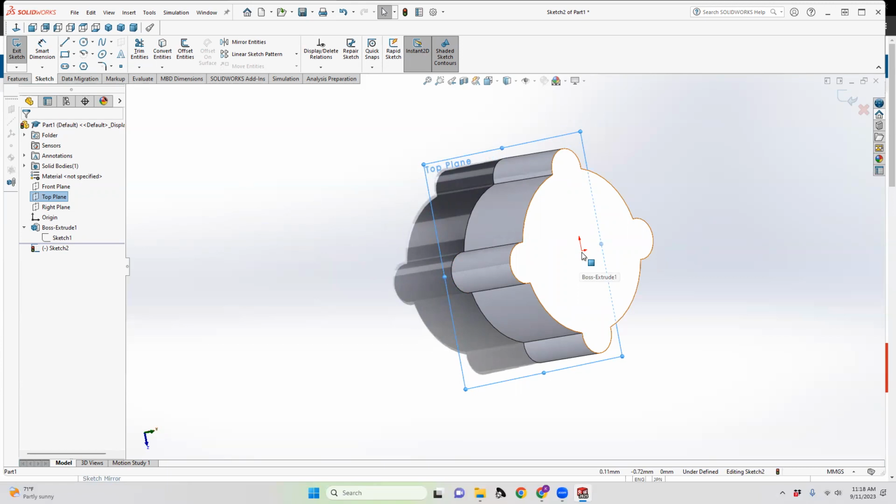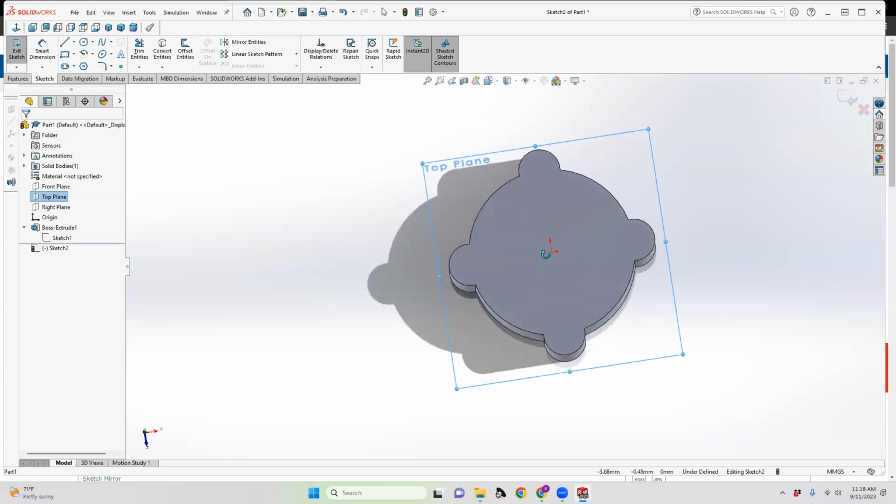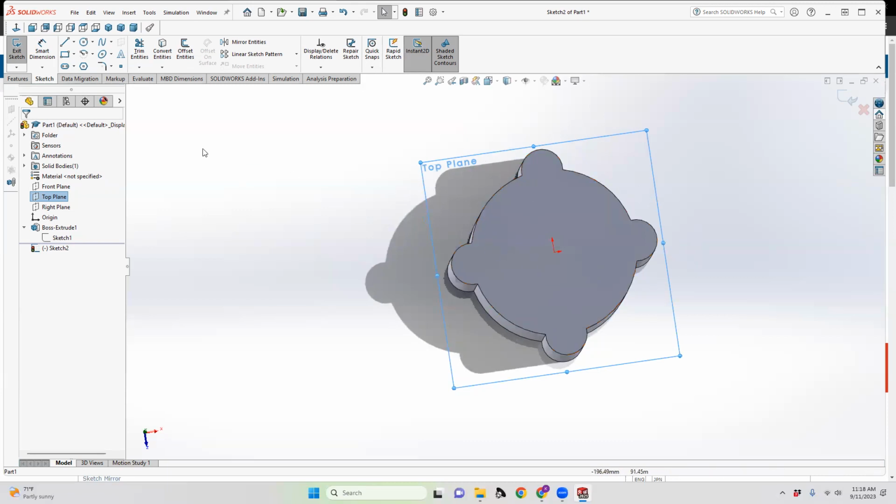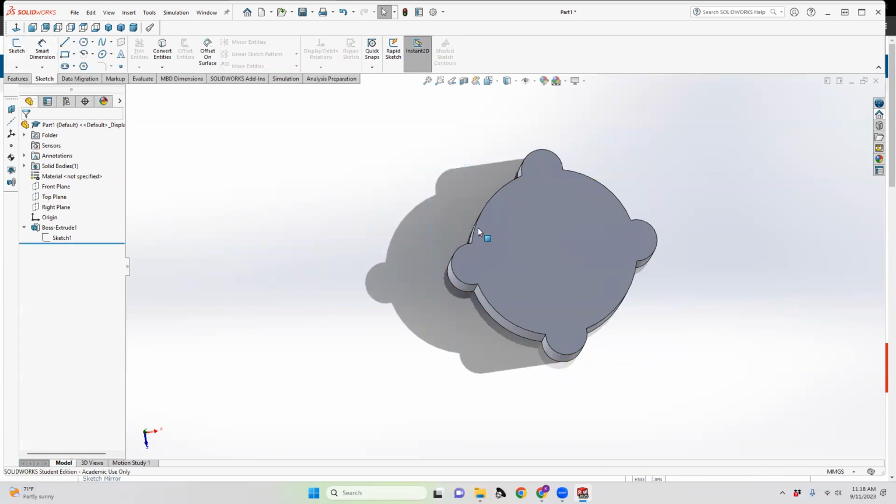That's useful for some things later, but the problem is if you have to modify this feature too much, you can lose some reference points. So we're going to start learning that everything on a sketch needs to be done, if possible, on the fewest number of planes themselves. We'll learn some more about that later, but there's a lot that you can do with that.